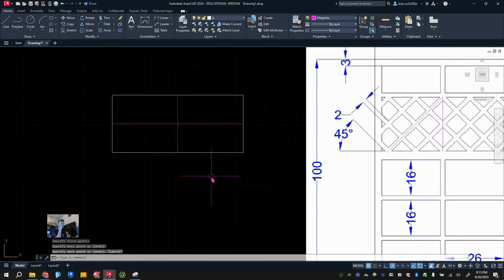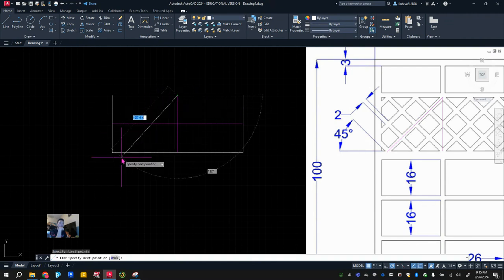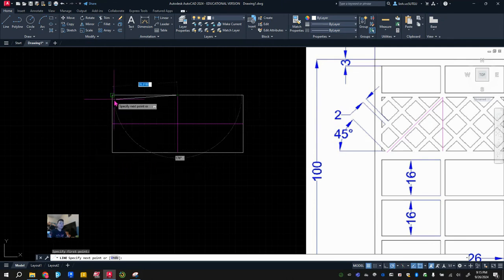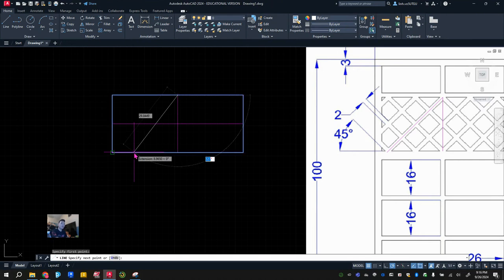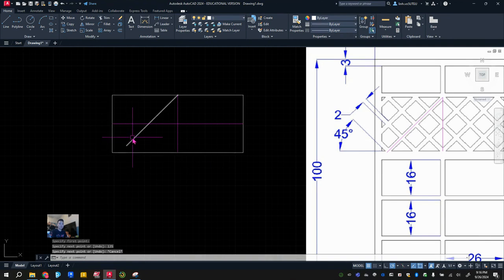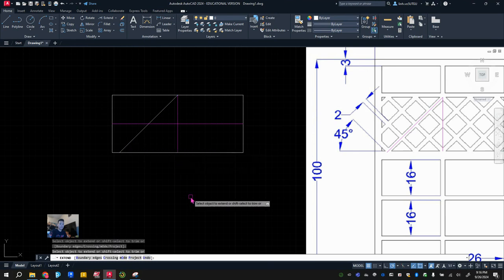Now, you can see that either center. And the next thing I'm going to do, I'm going to go to by layer. So make sure that it's in white. I'm going to go to that center. I'm going to construct an angle that is this right here is 180. I want this to go all the way to this line in the bottom here. I'm going to hit the tab key. So I want 45 degree. 180 minus 45 is 135. All right. Now it did not go all the way in there. I can just click on the drop down, hit extend, and voila, I have it.